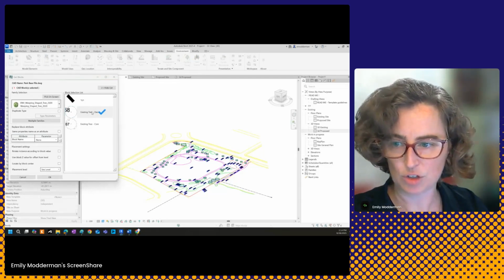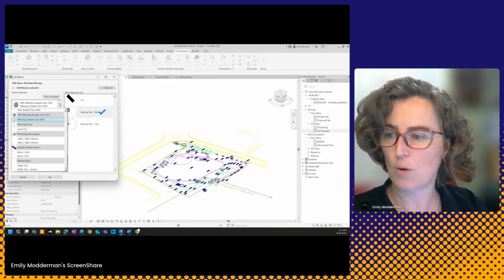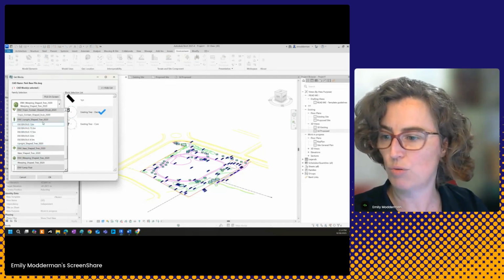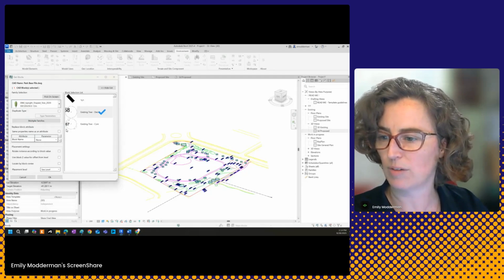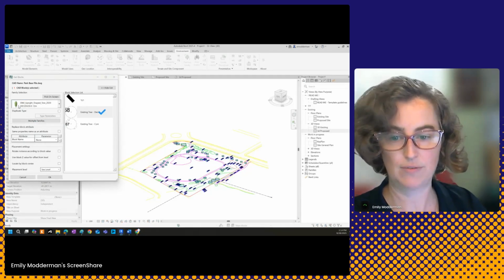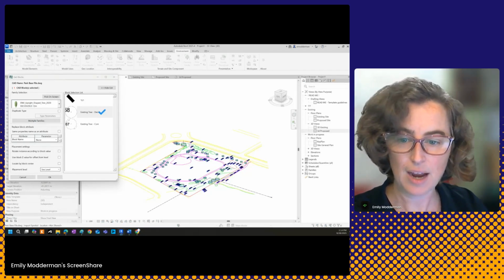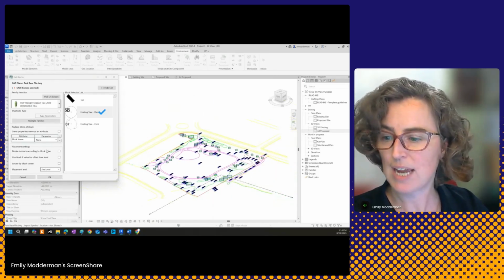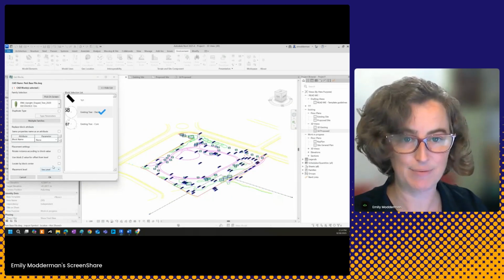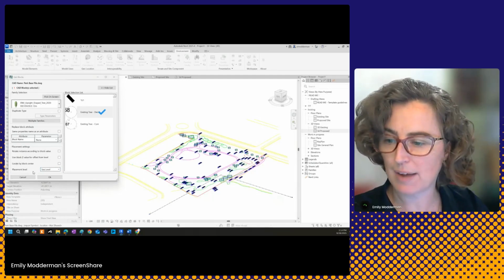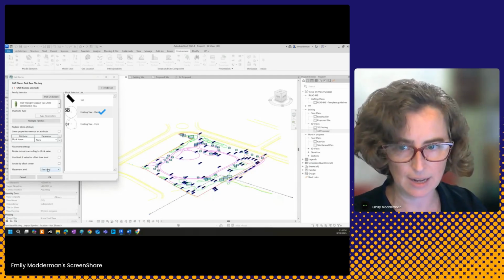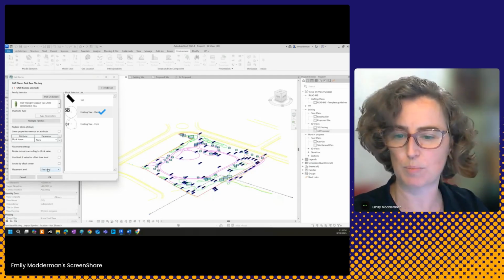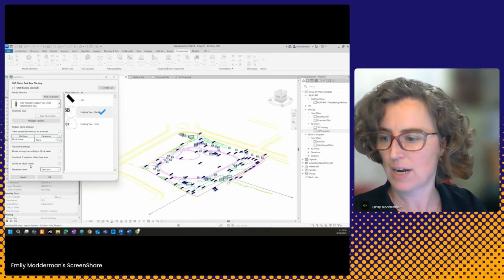I'm going to grab my deciduous tree in this list, and I'm going to map it to, let's say, a 12-meter deciduous family. It highlights all of those blocks here. I'm going to leave everything at default, but I've got placement levels, so I'm going to leave it at sea level because I'm going to show you another environment tool to pick those up from sea level later.